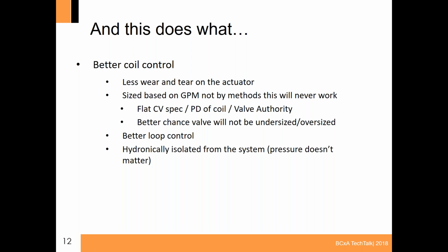So it might be opening more than it should and then closing more than it should as it tries to find a satisfactory control point. Well, that changes the demand required for the control loop. And if you've got some improperly tuned valves out there, the traditional method is a whole lot harder to control, and then that will screw with the main loop.